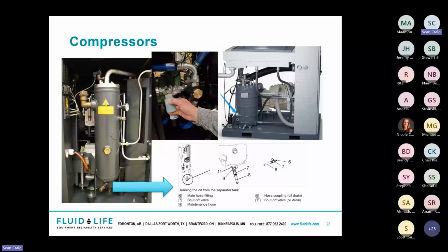Nonetheless, they're all special cases when it comes to oil sampling. These things tend to deal with high temperatures, usually some sort of gas contamination or intrusion, as the oil is forcing itself with air or whatever it is to compress it. And they sometimes have limited safe access points. In those cases, these things are enclosed.